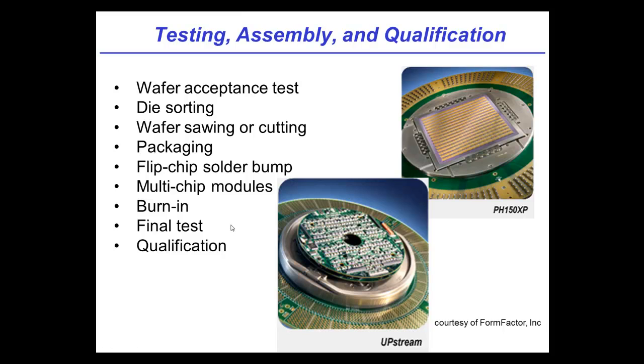Just to give you some ideas of some of the testing that we do. For example, one of the tests is a fail or pass test, a go/no-go test, where you'll test your chips to make sure they work, because you don't want to ship a dead chip to a customer. Of course. So that's one. But there are other tests as well. So for example, you know that when a new microprocessor comes out, it often is available in 2 speeds.